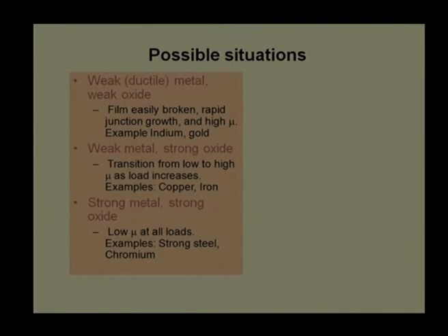Here, when we talk about a weak oxide layer, it is not in an absolute sense, it is only in a relative sense. This layer is attached to the ductile material, and the strength of that layer over the ductile material is low. We are not talking about any other thing; the attachment or adhesion to the parent ductile material is weak. That means it will simply be removed or abraded or delaminated if there is some surface roughness or some tangential force applied by a harder surface.